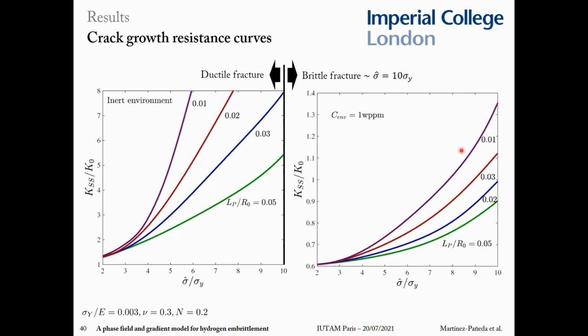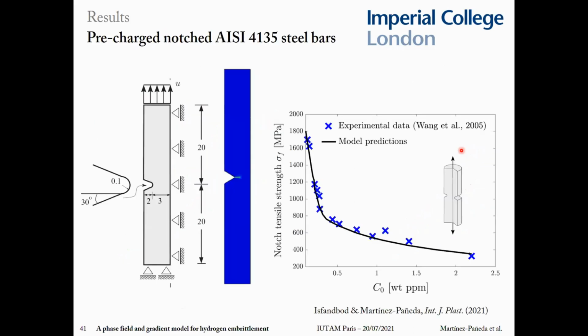Otherwise, as you know, in conventional plasticity, your stresses are too low. You're always too far away from this brittle interface. And just to finalize by showing some representative results, of course, the beauty of it is that by being an enriched continuum model, we can also model large-scale problems, so we can validate our model with experiments.